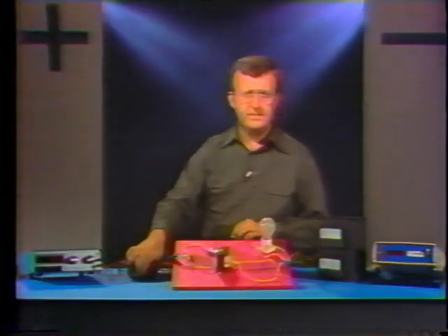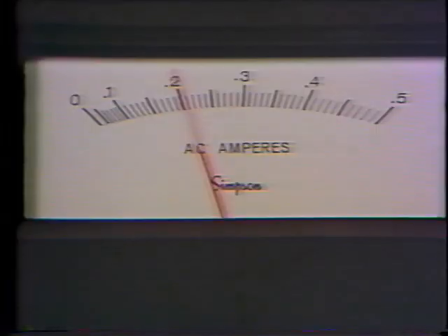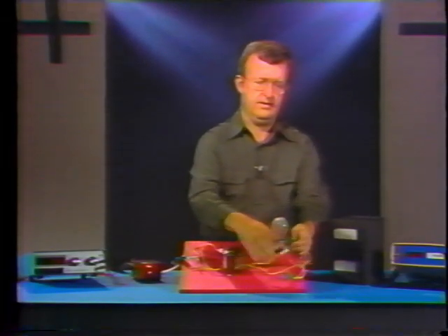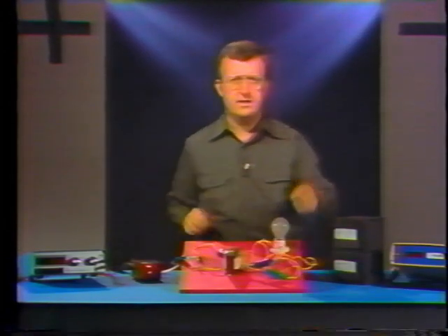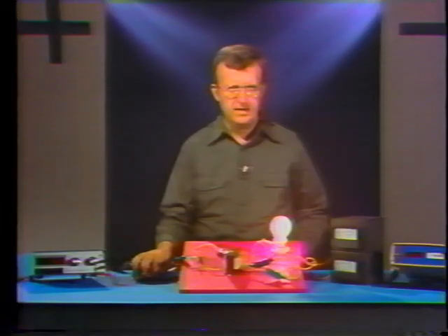Now, finally, I'll check the input and output current, and to do that, I'll use these 2 ammeters. First, I'll connect this ammeter to check the input current. Now, the ammeter gives me a reading of 0.2 amps. Okay, I will disconnect the ammeter from the primary circuit. And we will take this ammeter and connect it to the secondary circuit. And when we do that, we can check the output current. The output current is just about 2 amps. The output current is 10 times as much as the input current, but the output voltage is 1/10 as much as the input voltage. Now let's look at why this is so.